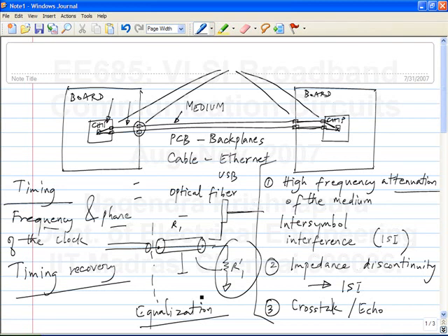So these are the main problems in communicating digital data, right? These things always exist. When you send data from one flip-flop to the next, it exists. But of course, you don't even think about it because you send the same clock. That works because the one flip-flop is synchronized to a particular clock, and you can use the data out and the same clock, and the next flip-flop also gets synchronized to the same clock.